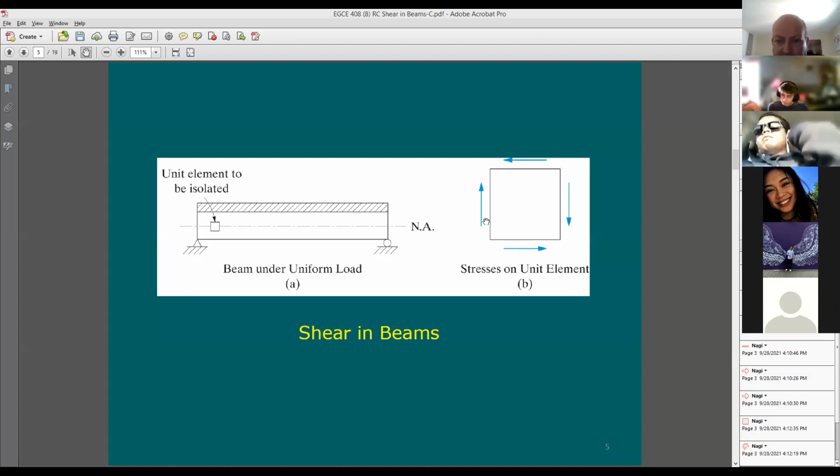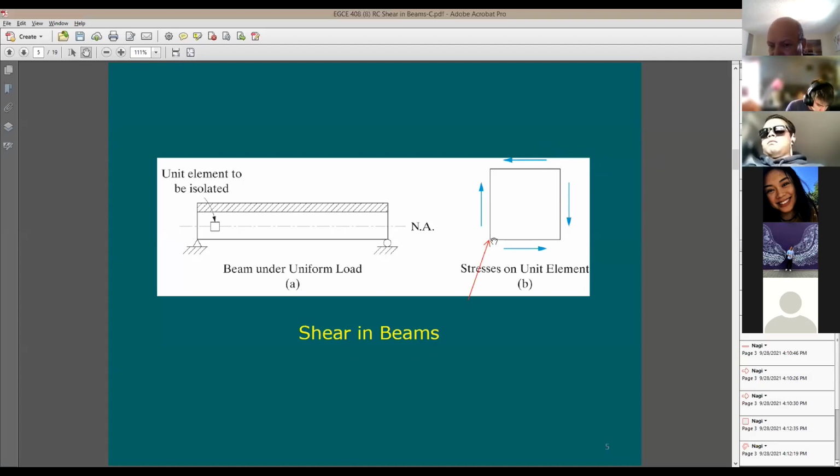So back to our discussion on the stress element. When you take summation of the force in the y direction, the x direction, and summation of the moment at any point to be equal to 0, you'll end up by taking the moment about this point. You find out that you really need to have this conjugate shear component. And by doing this, in this spot, you see here that these two components will end up to a resultant is going to be in this direction, another resultant is going to be in this direction.